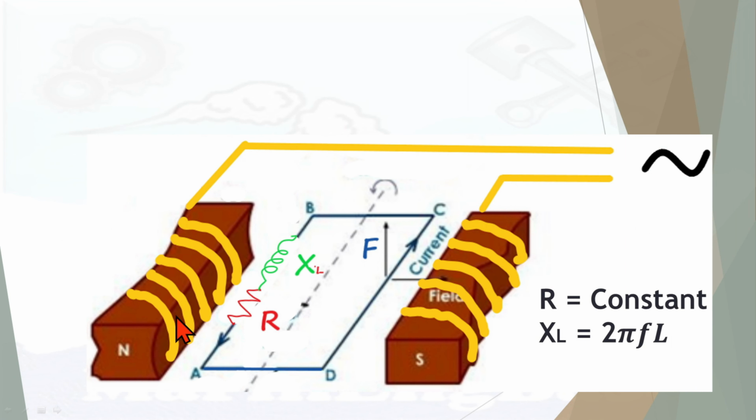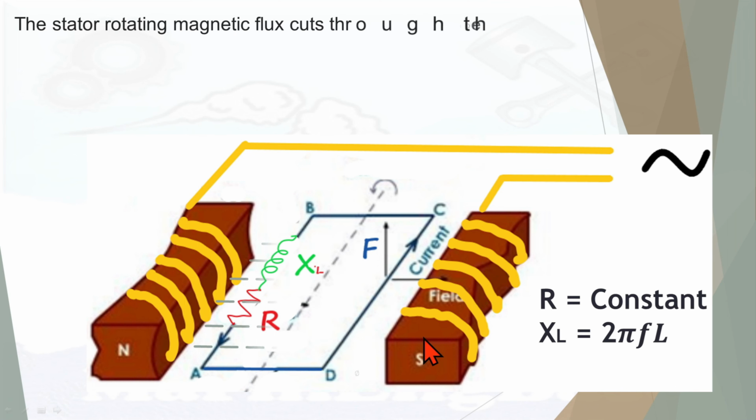If we dig further, we can see this diagram. These two are the stator winding, one phase, two poles. Suppose in the positive half of the supply this one creates a north pole and this one a south pole; in the next negative half cycle it alternates, so this one becomes north and this one south. Anyway, there will be a magnetic field acting from north to south.